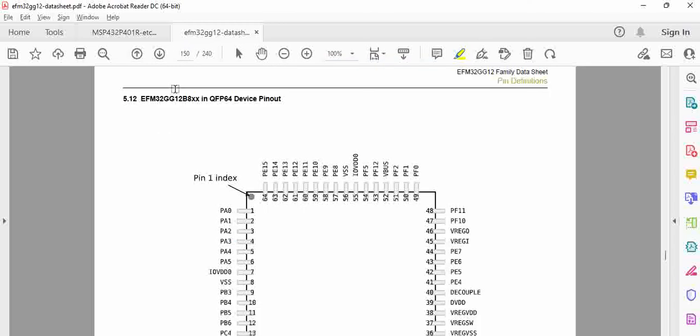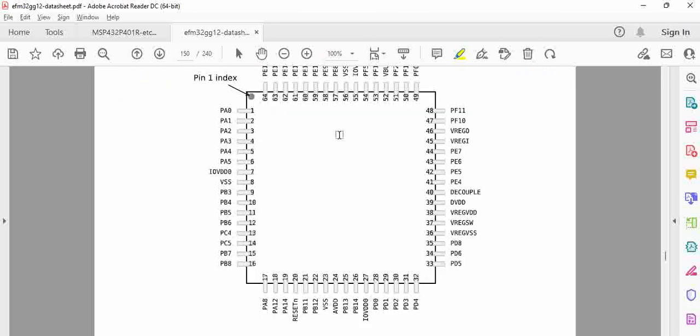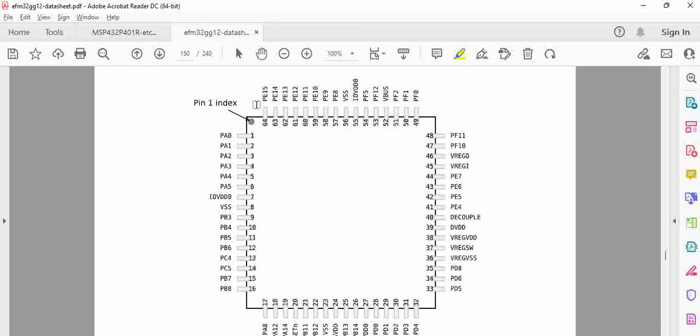Then we will see the actual pinout. So if you go to this pinout, QFN64, this is what we are using, right? So you can see here there are 64 pins that are available, and you can see most of them are right now shown with a port number, P0, P15 kind of. But for example, if you take the PA0 pin, PA0 shall have many functions,